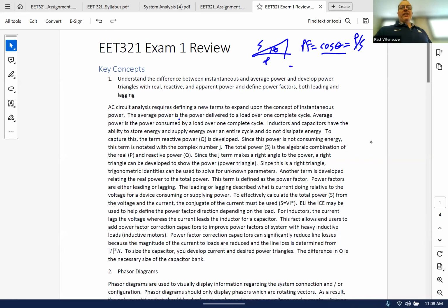So let's say it's 30 degrees, and if it's a lagging power factor, I will draw this: the inverse cosine tells me the 30, and I being below V, or lagging V, is because of the lagging. I get the angle, I note it, and then I draw it that way. If you get more comfortable, you can start to say, oh, I know it's plus or minus with I or S, but you can get easily confused if you just try to put negatives in there, because you could put a negative when it really should be positive.